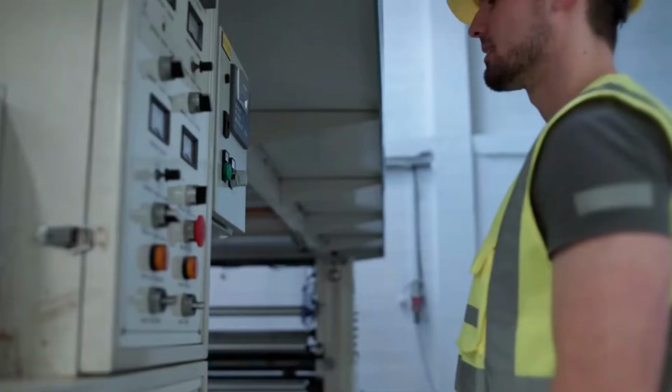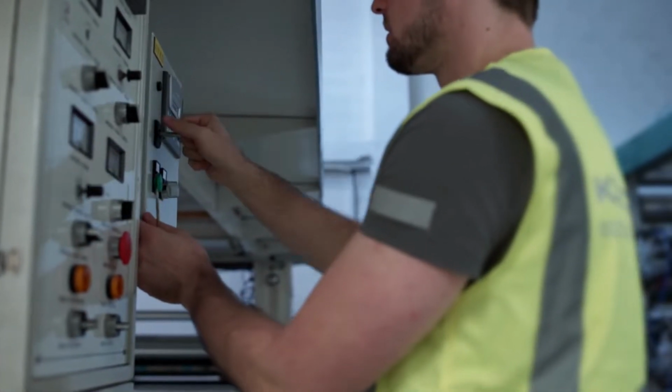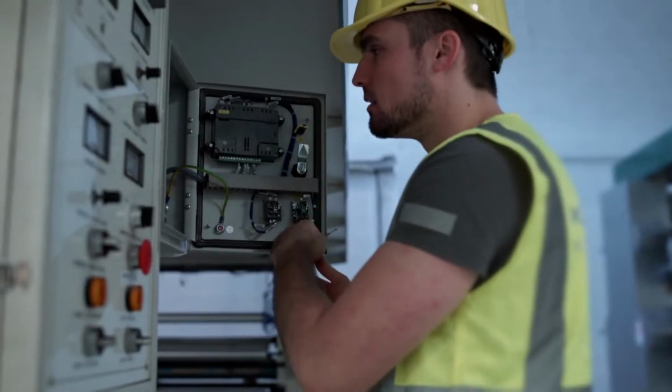Shock protection boundaries, identified as the limited approach boundary and restricted approach boundary, should be applicable when approaching personnel are exposed to energized electrical conductors or circuit parts. NFPA 70E's tables are used for the distances associated with various AC system voltages. NFPA 70E Table 130.4(E)(b) is actually used for the distances associated with various DC system voltages.